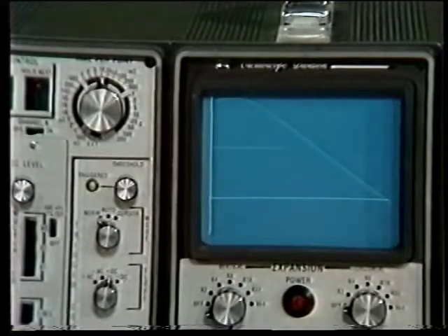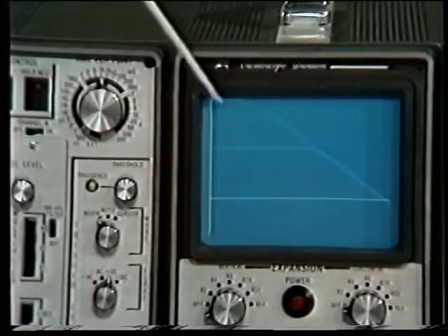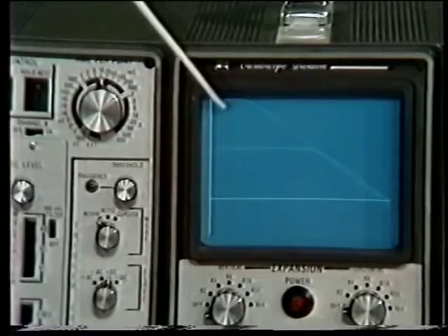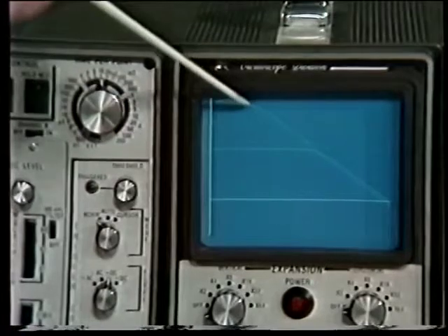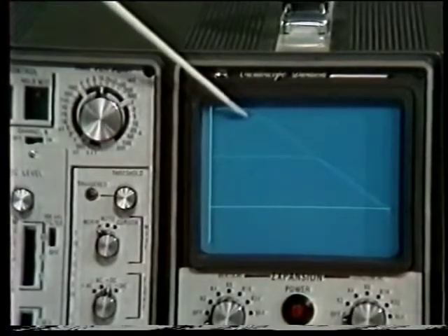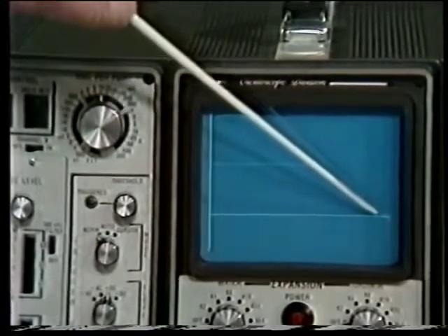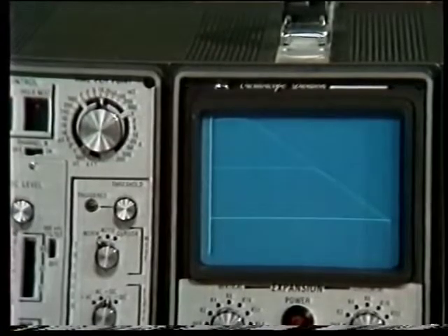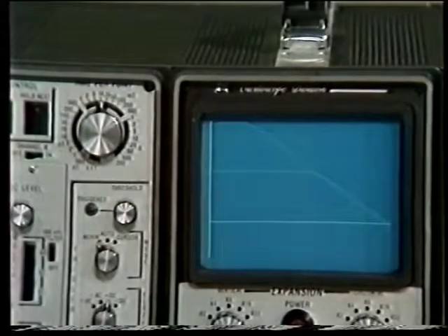Now back to the first curve. This horizontal portion is the open loop gain. It's 80 dB, that's a gain of about 10,000. The gain has dropped by about 3 dB, that's a 3 dB point here, at a frequency of 100 hertz. And the gain drops to unity, that's 0 dB, at this point, which is at around 1 megahertz. I confess that I've designed this circuit to give nice round figures to make life easier for me.